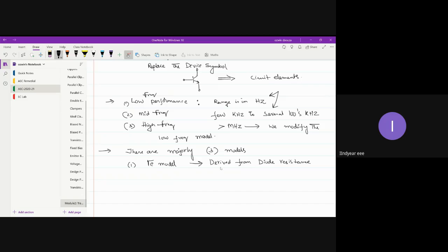In case of a diode circuit, the AC resistance, or the effective resistance small re, can be given as 26 millivolt divided by the DC emitter current IE. So on the input side, the P and N layer, the PN layer, is basically your diode layer, right? A diode is a PN junction semiconductor device.